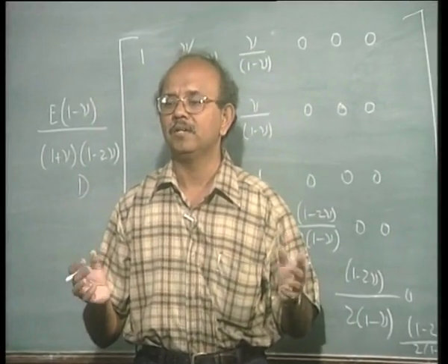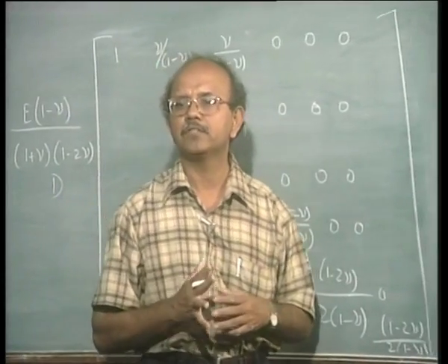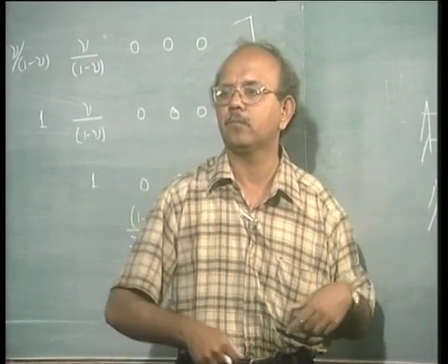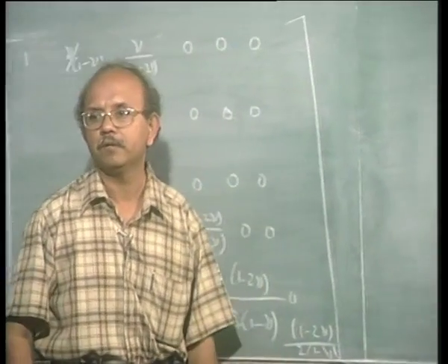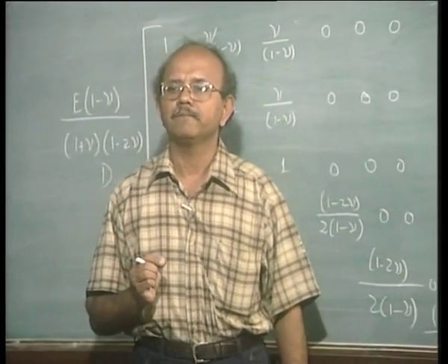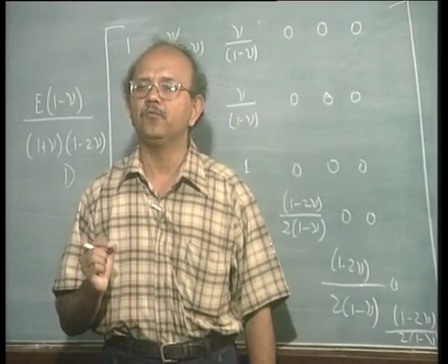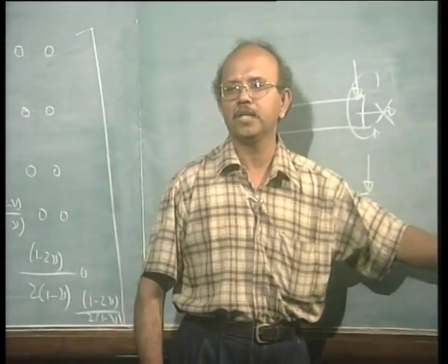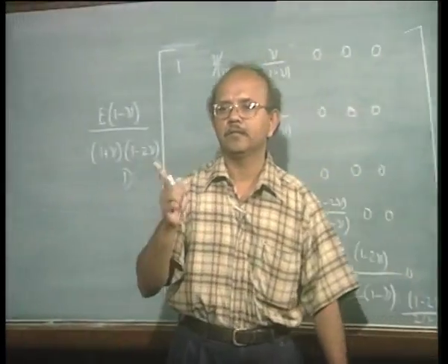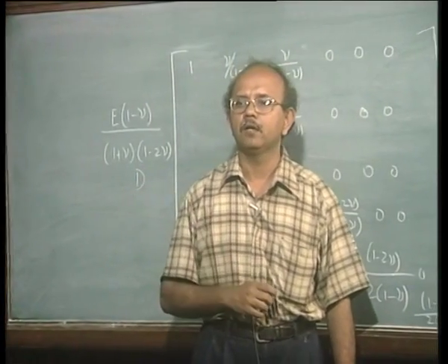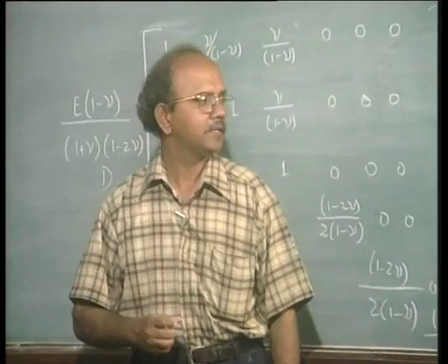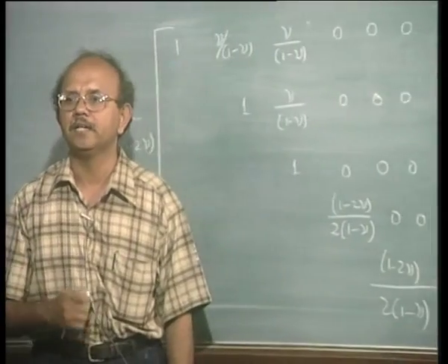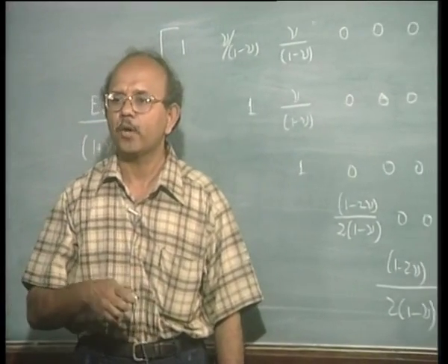Okay? So that degree of freedom is called the drilling degree of freedom, because it's something like perpendicular to the plate or the shell, and hence drilling degree of freedom. But unfortunately, we may not deal with only planes when we deal with this kind of shells. In fact, the same shell that you saw as an example in one of the slides, the side wall sheet, is not a plane like this. When you look at it from the side, it is not a straight line. It has quite a complex shape.